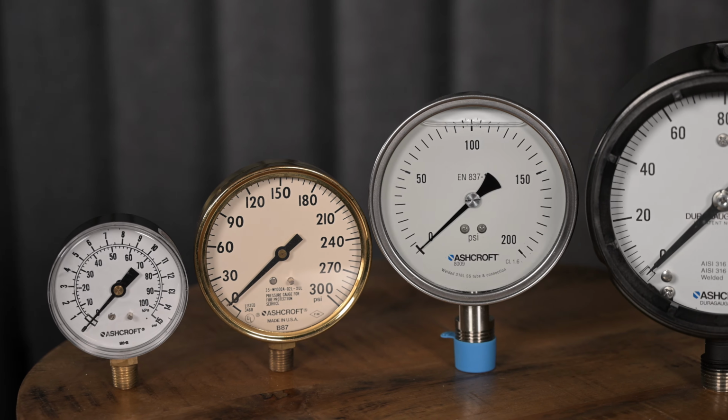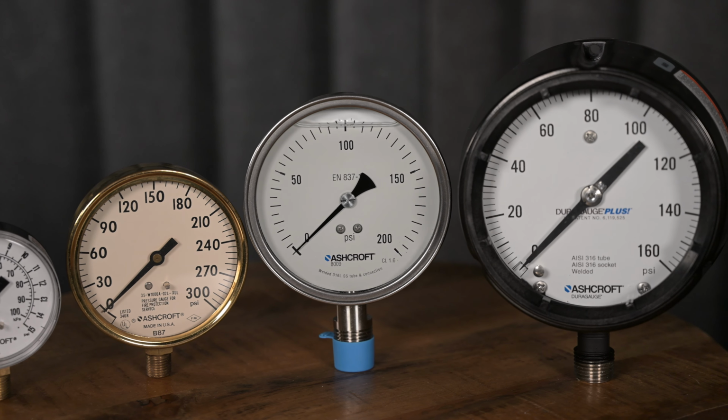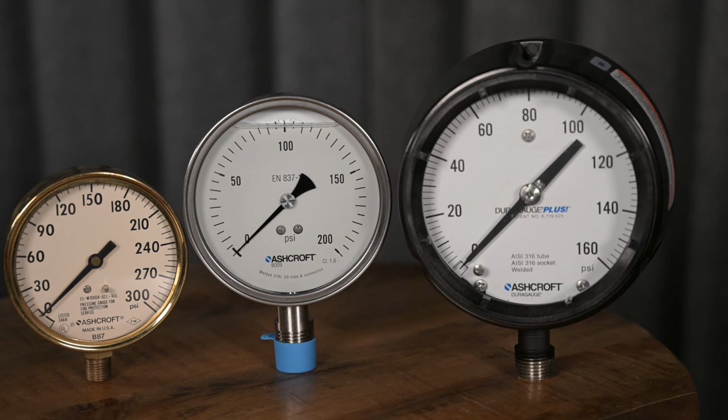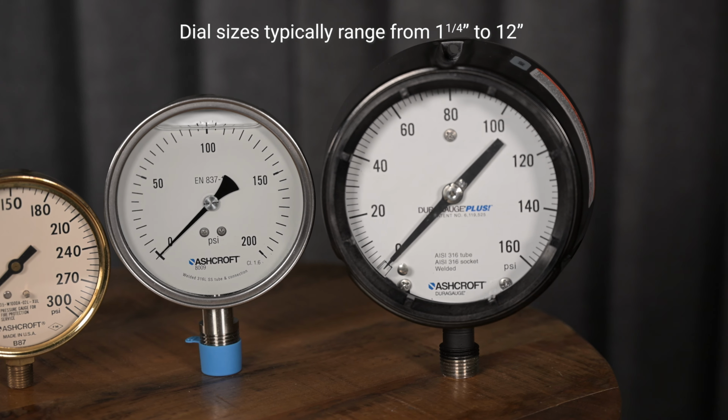All pressure gauges have a variety of dial size options and features to consider. Depending on the range you need, dial sizes typically range from 1 1/4 to 12 inches. Gauge size and readability are very important considerations. You can narrow down your options by asking yourself, do I need to read the gauge from a distance? How far away is the gauge from the operator?